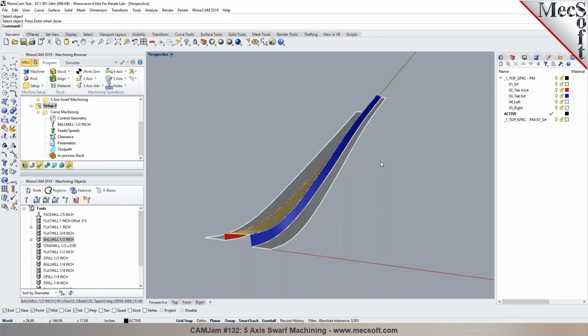Like sometimes we will post-process a file, and then once you try to execute, you will get an error saying that your toolpath is either going out of the limits of the table, or that there's some singularity being detected. Okay. So when we post-process, we let you know if your output is outside of the limits in terms of the primary and the secondary axis angles.